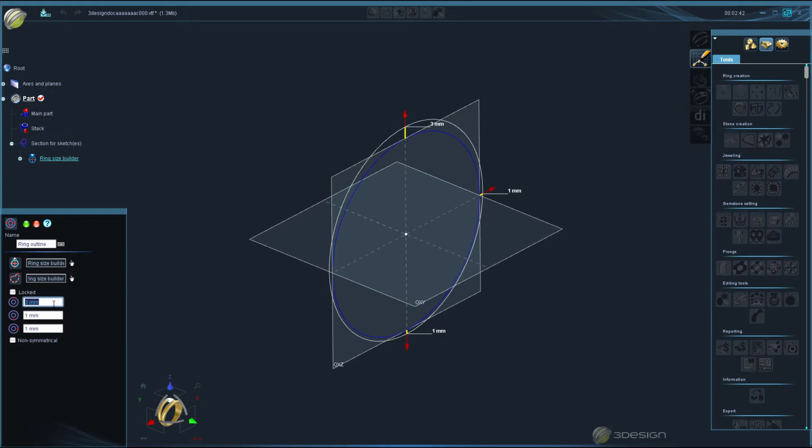So that means our height for the bottom and top are going to be 0. So it'll stay 50 millimeters. And then we need to add 6.5 millimeters. That's half of that 13 we talked about for the sides. That gives us 13 millimeters total wider than the height of our ring size builder.